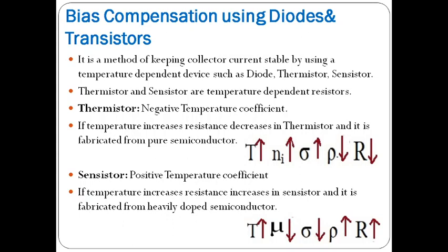Sensistors have a positive temperature coefficient. These are fabricated from heavily doped semiconductors. When temperature increases, the resistance offered by the sensistor also increases. Why?